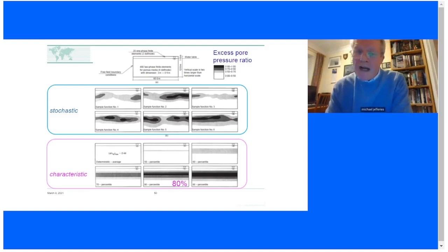The random choice of void ratio honors the standard deviation and the trend of mean that we see in the CPT. So we're replicating the statistics of our sand. Now, of course, it's a statistical business. So that's why we roll the random number generator, and each time we roll it, we'll get a slightly different distribution.